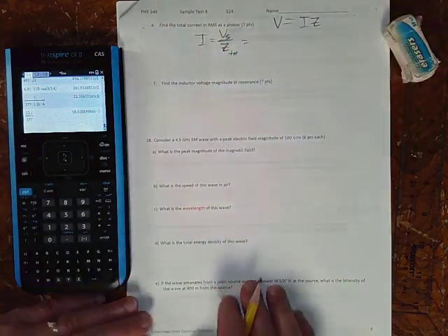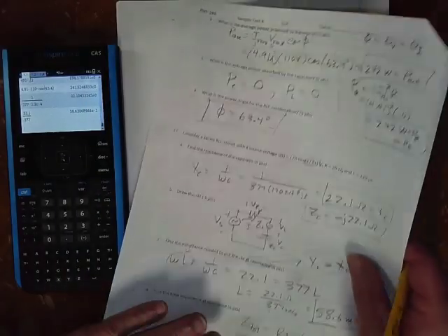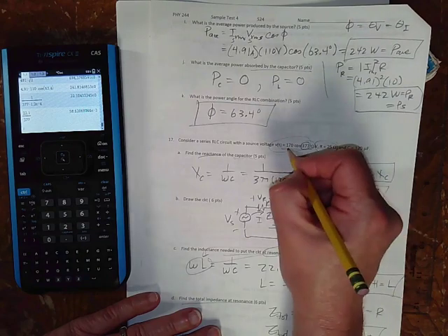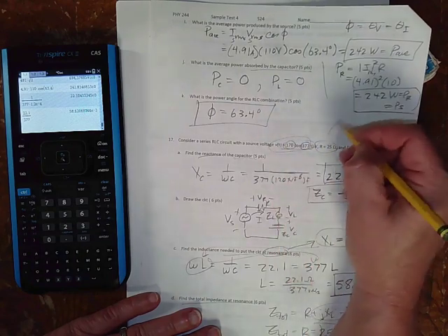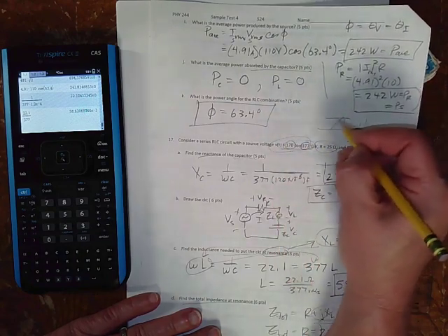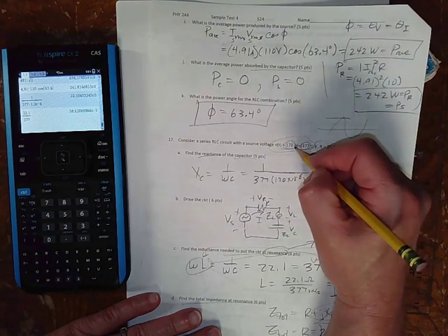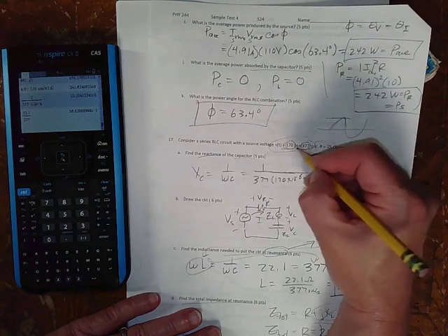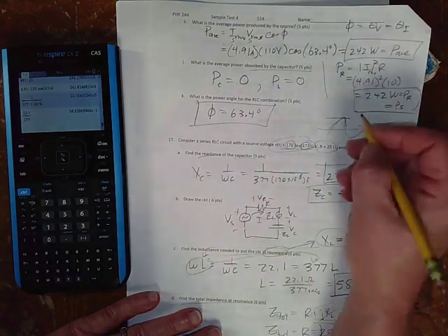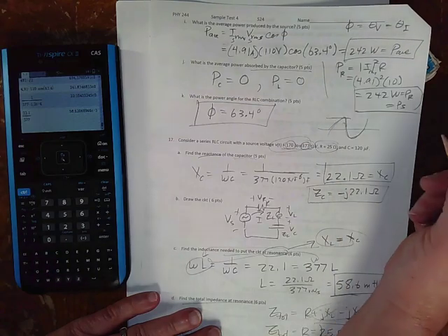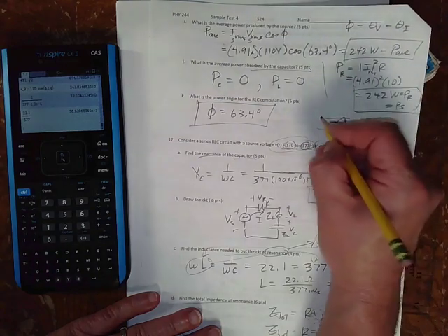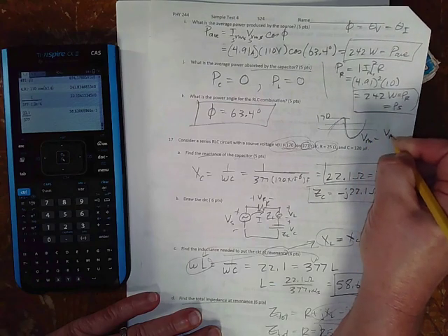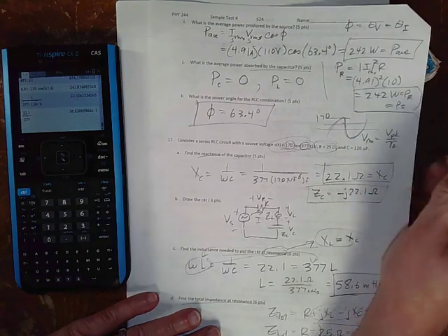To get the source voltage as a phasor, remember, whatever's multiplying the cosine is the peak. When we draw a sine wave, usually it would be sine, but if we start with cosine, just make everything cosine and it all works out the same as if we had done it with sines. So the peak value is 170 here. We want RMS, so V RMS is V peak over square root of 2.